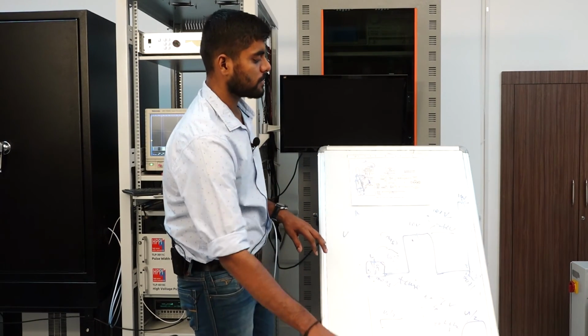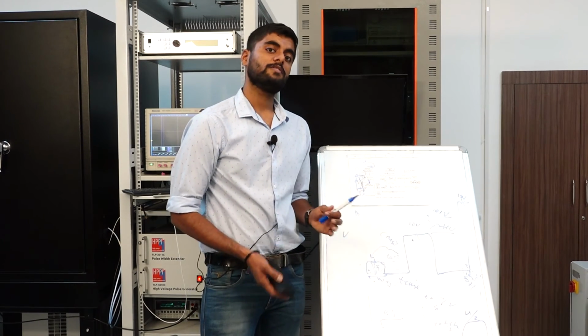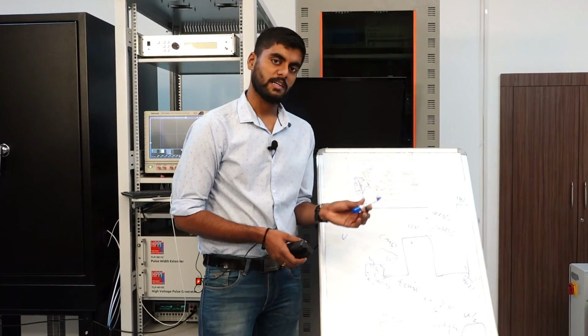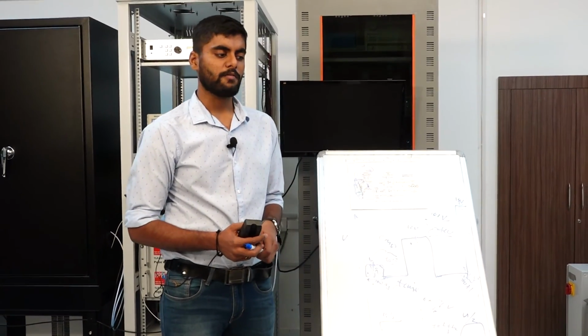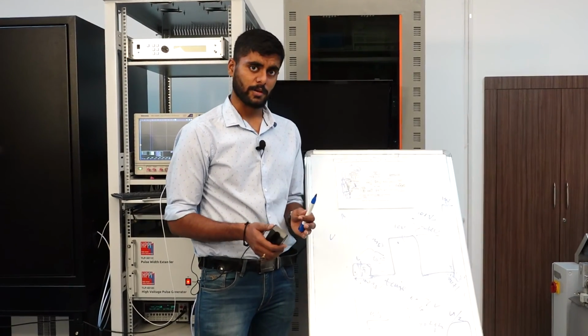So this is how the voltage signals are applied in your TLP generator, and that's why the TLP offers more physical information compared to other characterization techniques involving HBM, CDM and MM. While it may not give you the correct qualification values, it gives you a lot more information about the physics of the device operation.